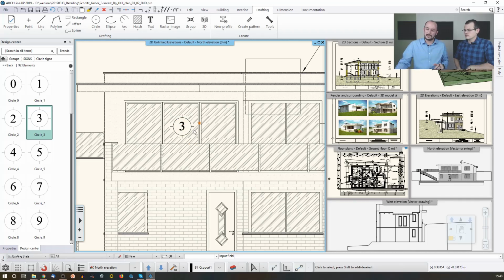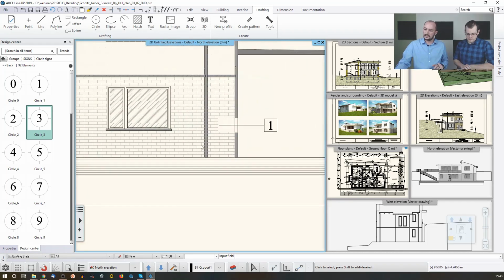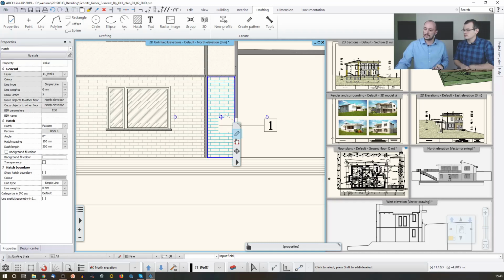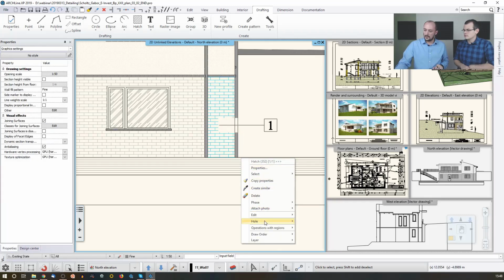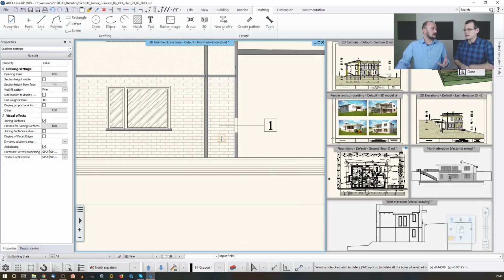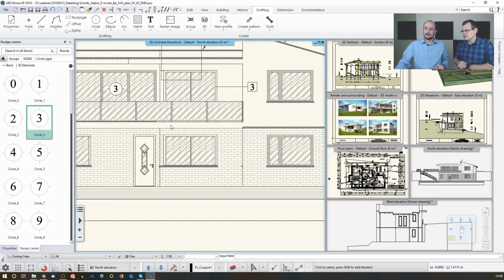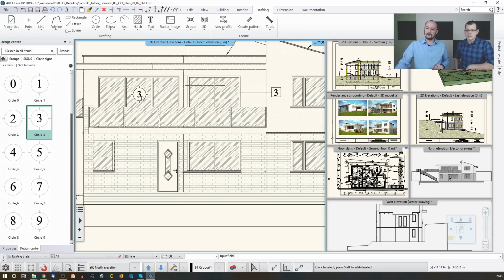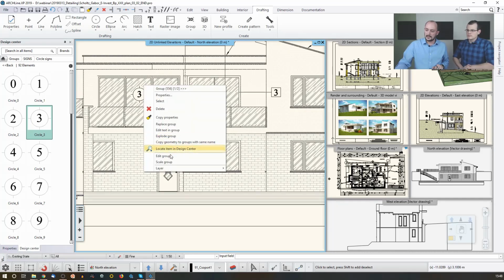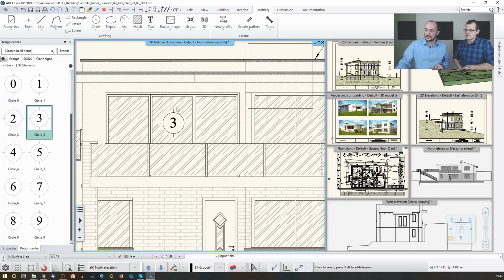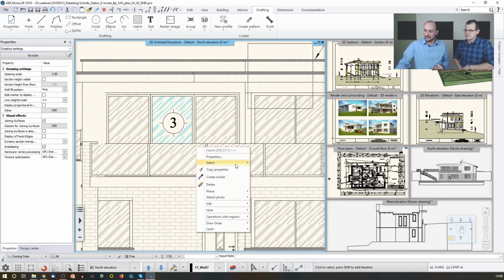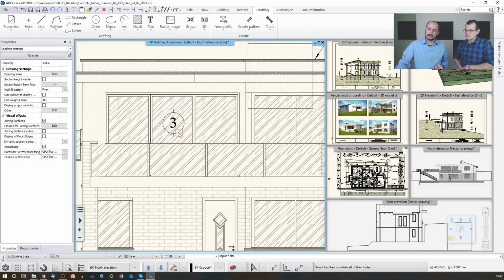And the same reason is behind what you can see here, to make things easier to understand, and those are holes in the hatching. So you can just click here, find the hole command, and delete the hole. And in that case, it will be cleared up. You can do the same thing. If I do the same thing quickly here, edit, that's a group. Let's just go here. This is the hatch and hole, and delete all holes. So I don't have any holes.